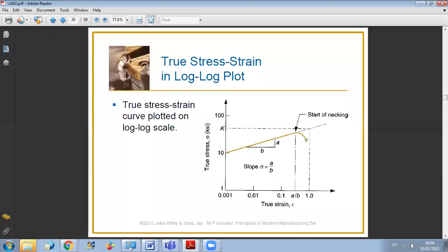We have seen last time that in the plastic region, we have a strain hardening zone, which will follow a linear profile in a log-log graph. Okay, and we have seen that n will represent the slope of this linear variation, and to determine the value of k, since this is a log scale, here we represent log of sigma, and here you have the scale log of epsilon.